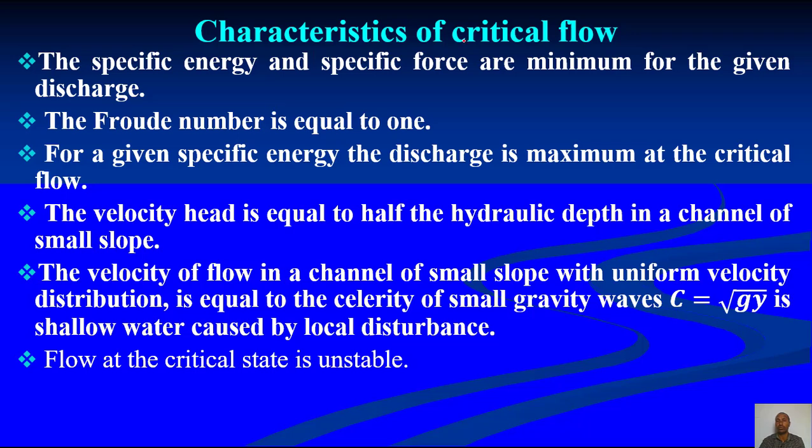So, characteristics of critical flow. What are the characteristics? The specific energy and the specific force are minimum for the given discharge, and the Froude number is equal to 1. For a given specific energy, the discharge is maximum. The discharge is maximum at the critical flow.